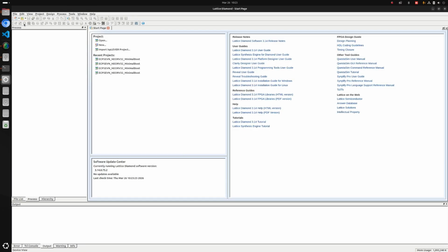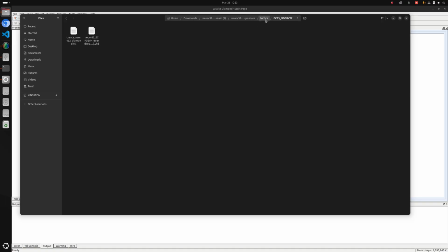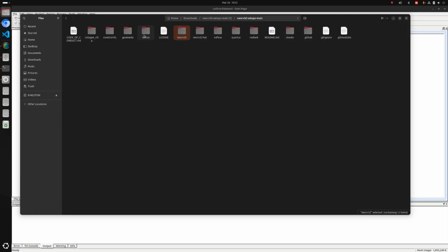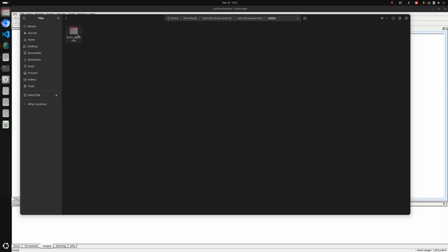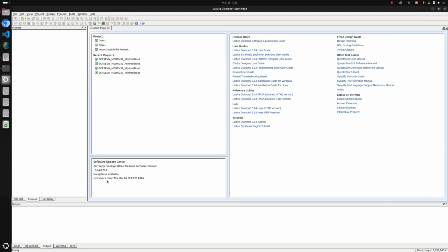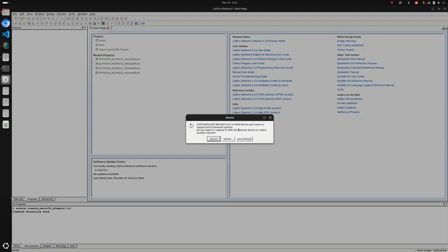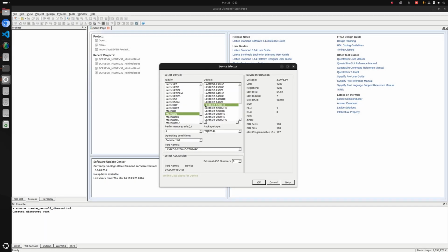Before we run the TCL script, it's necessary that the file structure is maintained, which is NEORV32 is exactly here relative to the Lattice folder. Otherwise, the script will fail. Alright, so going back to your TCL console, source NEORV32 TCL. Run it. See, it's throwing this error.